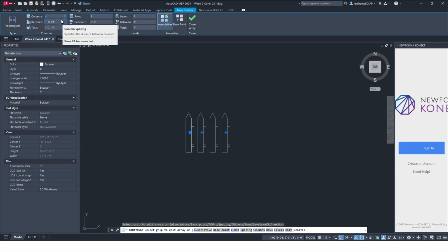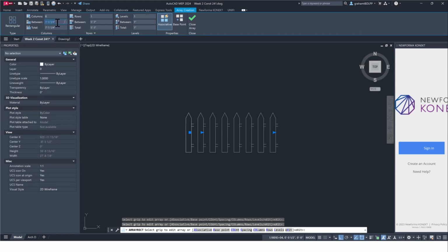So now I know that I want 1 row, columns. I'm going to do the same as I did before. I want a total of 8 columns. Okay. And it's not I want to add 7 to this, right? So you wouldn't put 7 columns. You'd put 8, including the original array. Okay. 8 columns. And I want a total distance between them, right? Of 8.5 inches, right?